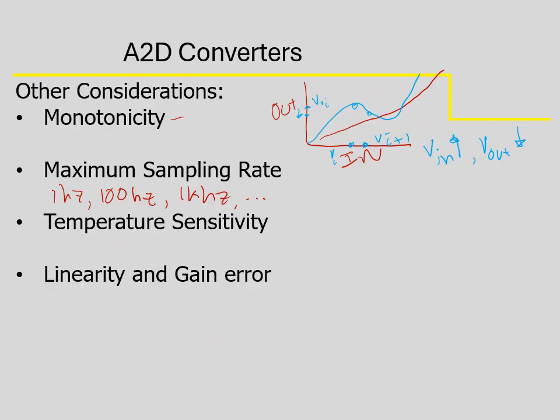You also may get lower resolution. There's usually a trade-off between resolution and sample rate. And it has to do with how we actually take the measurements. Okay, if you're recording more bits worth of information, it just takes more time.